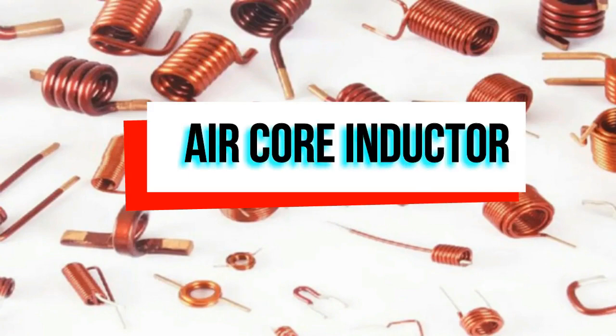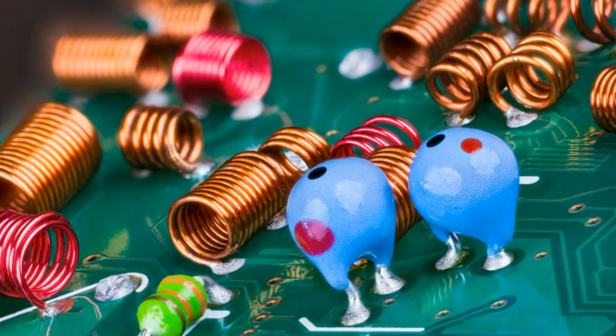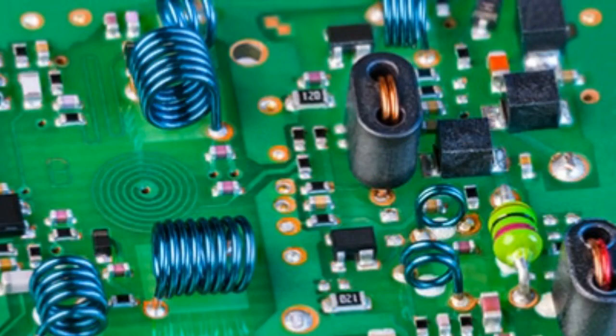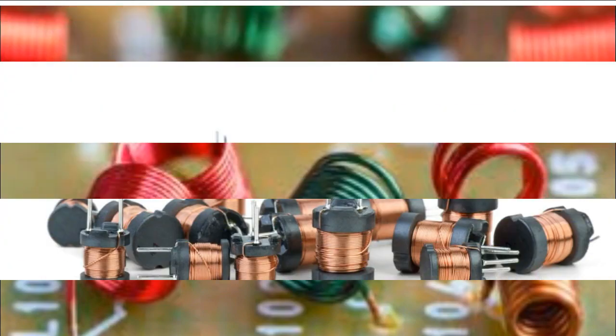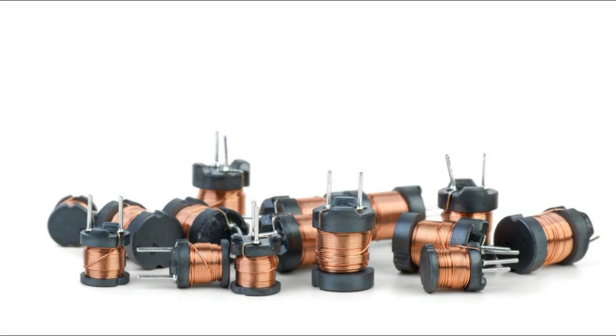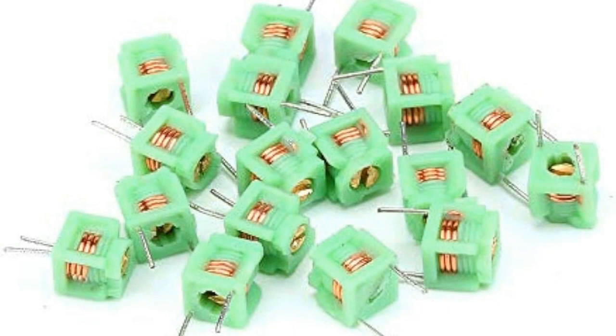Air core inductor. Air core inductors are hollow and are normally used in applications where the level of inductance requirement is very low. The fact that no core is used ensures there are no losses within the core and the coil is supported by the air. These types of inductors are effective in high-frequency settings. The core of these inductors is made up of plastic or ceramic, and so they are also known as ceramic inductors.